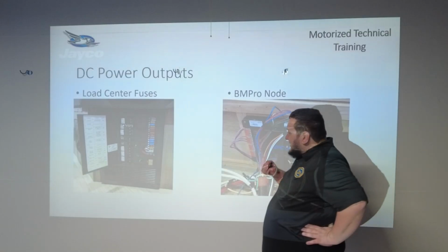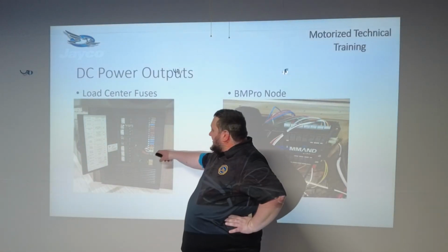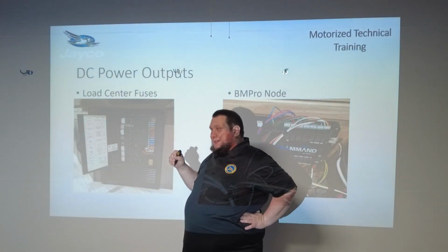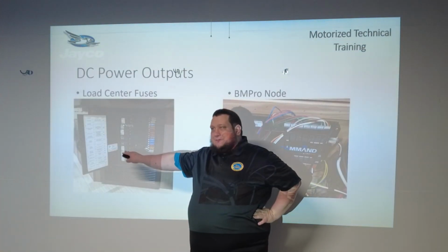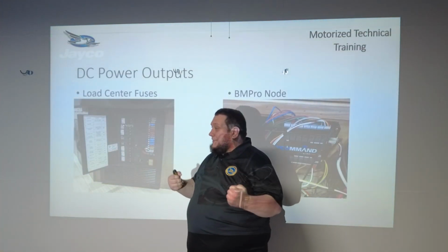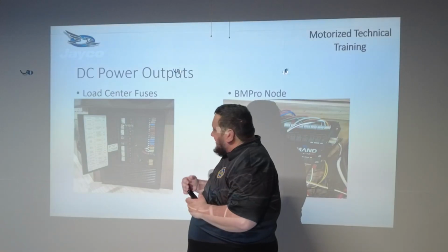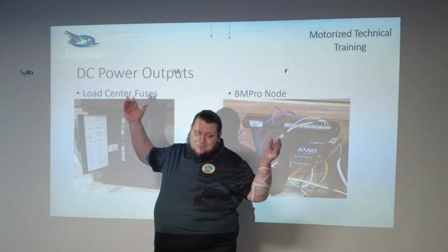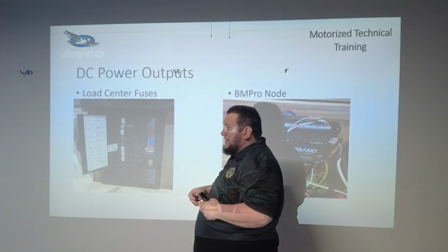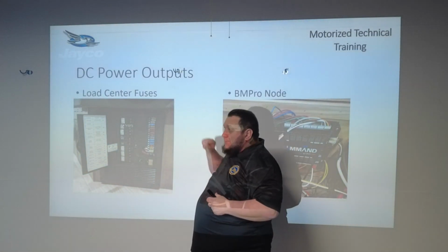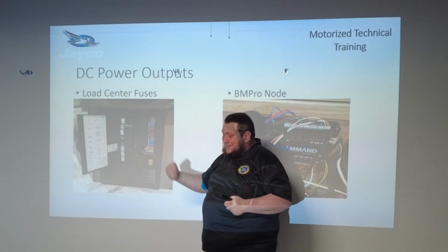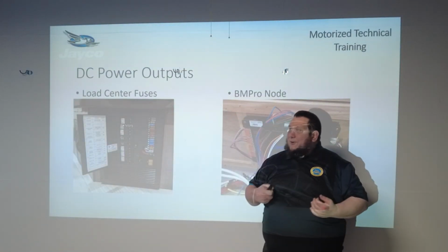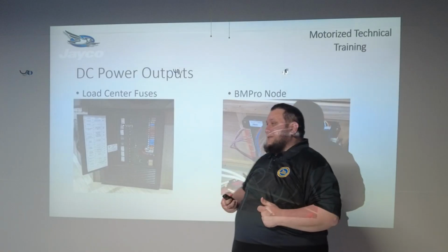Again, simply replacing a fuse does not address why the fuse blew in the first place. But that's a whole other realm of troubleshooting we're not getting to in this basic class. If the customer replaces a fuse and it's good to go, hey, we chalk it up to a loose connection that fixed itself. But if they keep blowing the fuse over and over and over again, we'll want to take it to a dealer to get it looked at and figure out what's causing that fuse to blow.